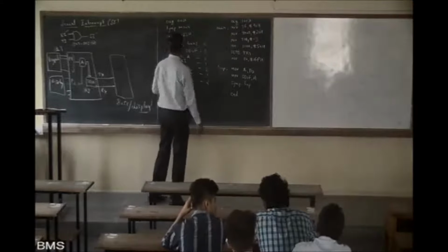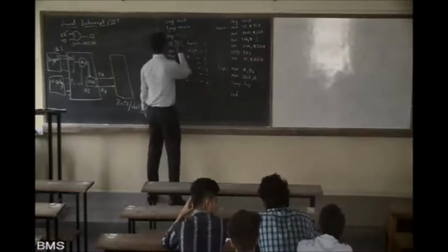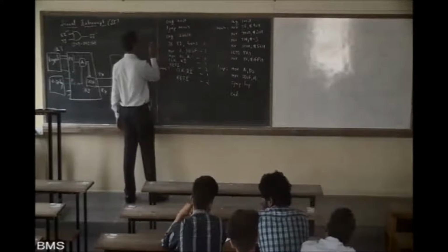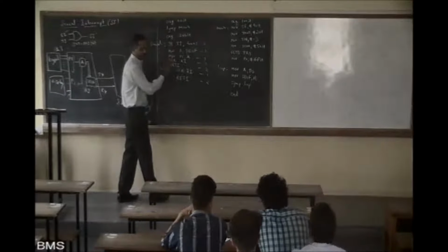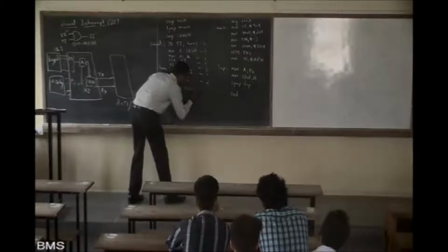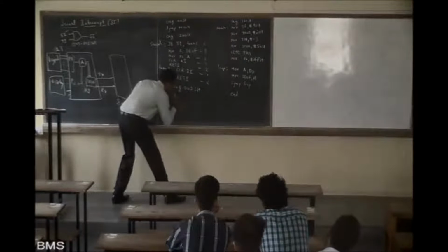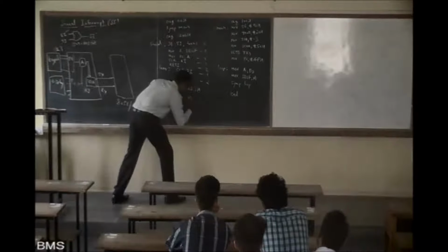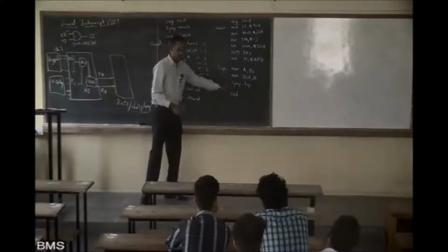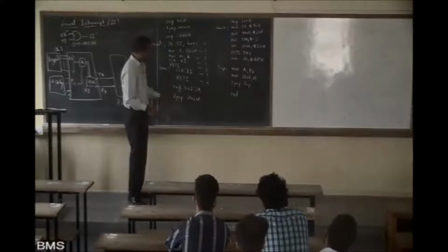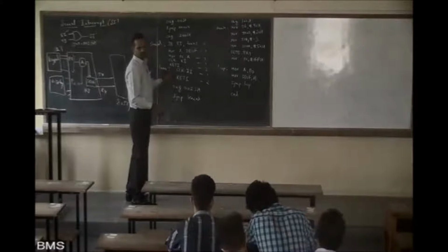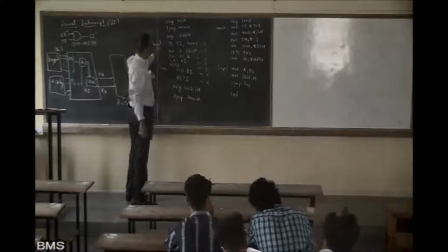So what you need to do is, 100 we have written there. Take 200H here. Guys, listen, don't write. Then here ORG 0023H, you just write LJMP to serial. You understood this? So whenever the interrupt rises, it will come here. Whenever it comes here, it says LJMP to serial. It jumps from here and starts. As it was more than 8 bytes, I have done it this way.